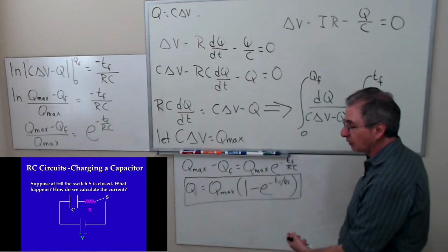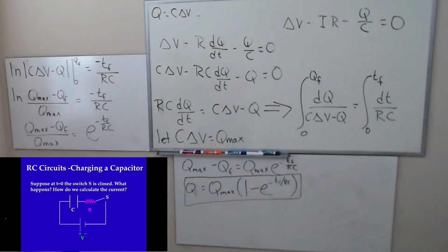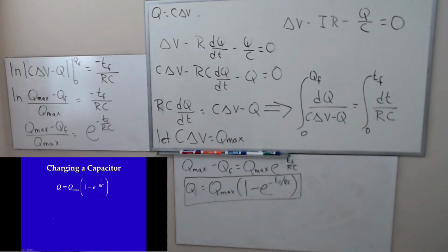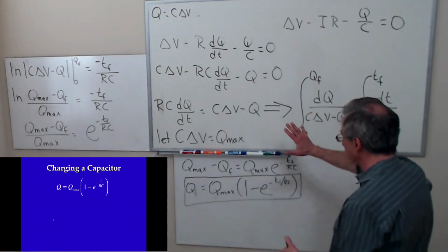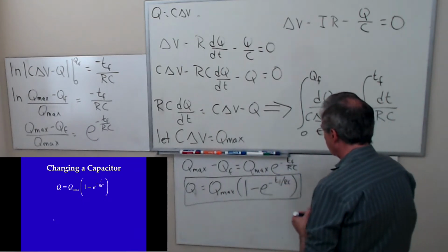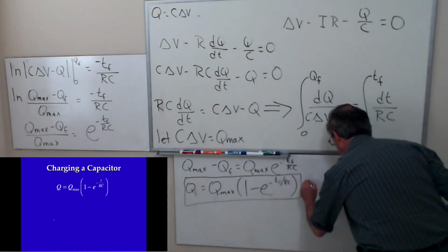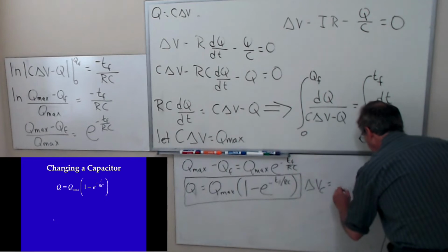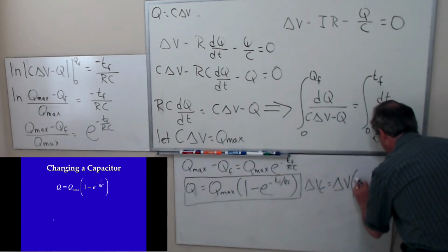All right. So this is the equation for charging the capacitor, the Q. But once we know this expression, you pretty much know everything else, because I can write the voltage across the capacitor as a function of time, because the voltage across the capacitor is this divided by C. And this is the battery voltage or the power supply voltage.